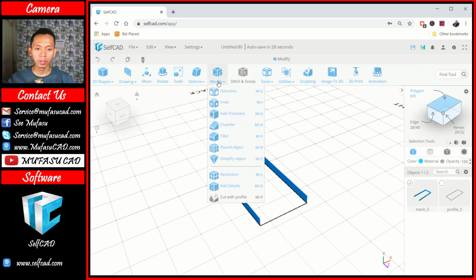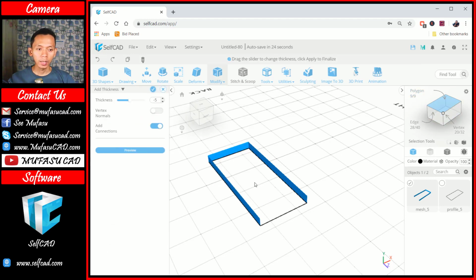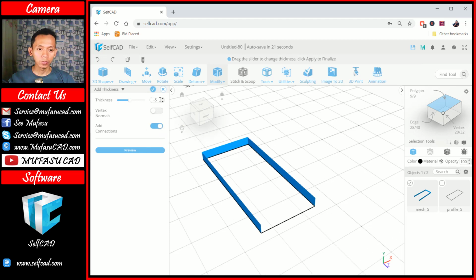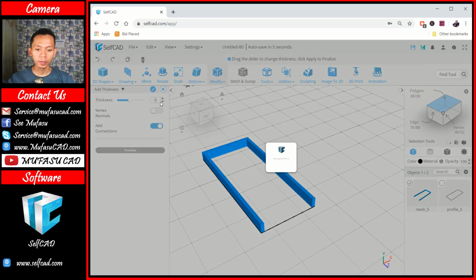You can use this add thickness option. In here we can set the thickness into -5. Okay, you can click for view. Okay, this is for -5. And then you can click OK to apply this add thickness.